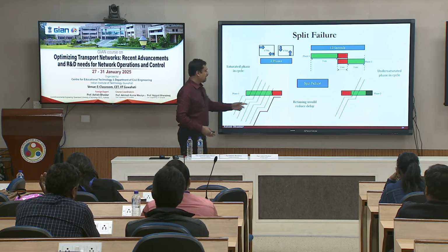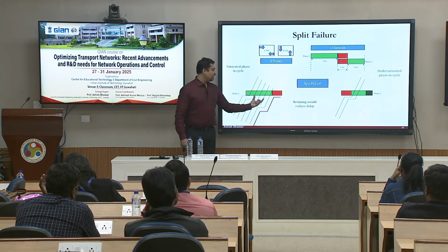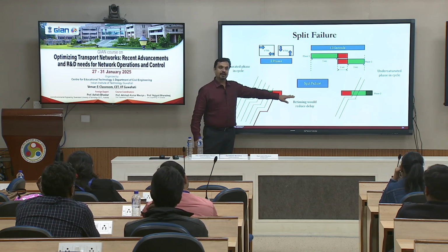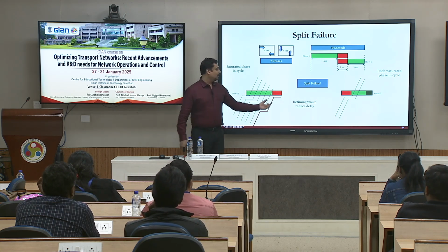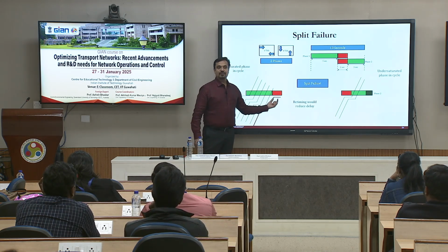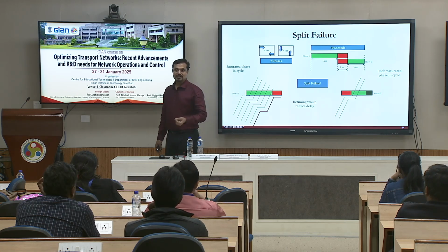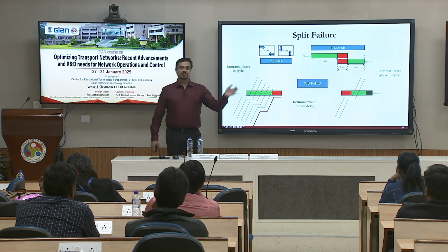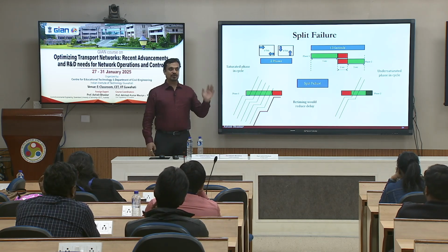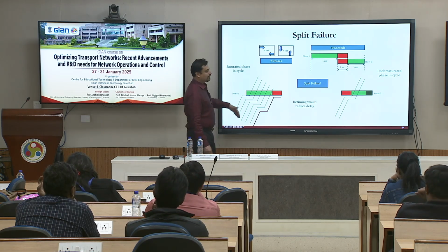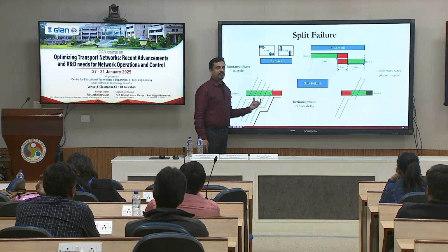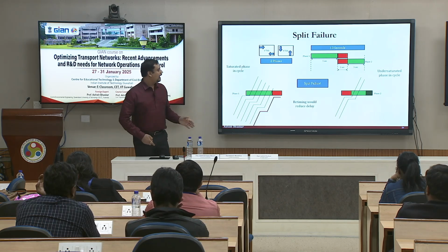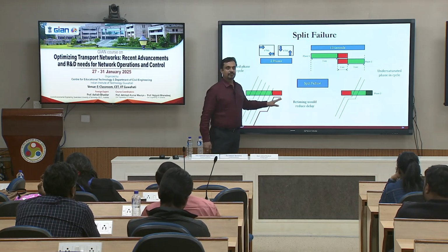So, in this particular case, you will have almost close to 100% occupancy for the red, high red occupancy, but in the first few seconds of red you will have some amount of occupancy also. In green, you will have occupancy based on the saturation you are expecting; a very good saturation occupancy means you had a good flush happening. So, you have some occupancy during green, and in the early red you have high occupancy also. So, you might have a high occupancy in this case for green and red.